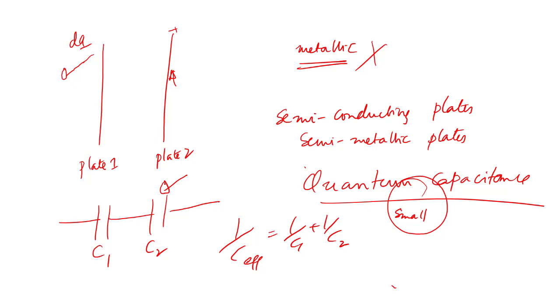And this is the reason why even in your computer chips, if you are a little tech savvy, you do know that there are these silicon channels going from one end to another end. So this is a silicon channel in the transistor in your chips in the computer, and depending upon this width, the quantum capacitance of this channel plays an important role. And as you're shrinking down to 7 nanometers and below, there is a technology that is coming up, these quantum capacitance effects are very evident, and those are not very easy to address. And that's going to be one of the challenges going down, in addition to lithography and other things.